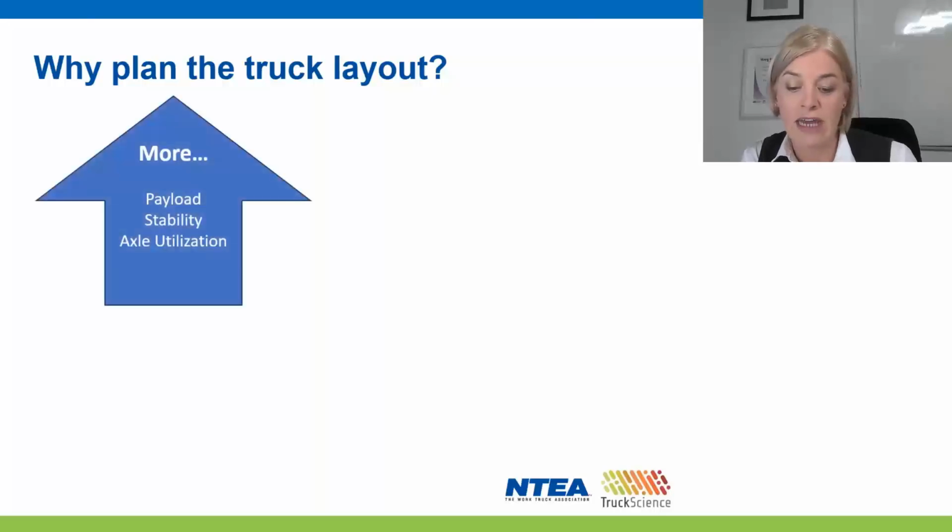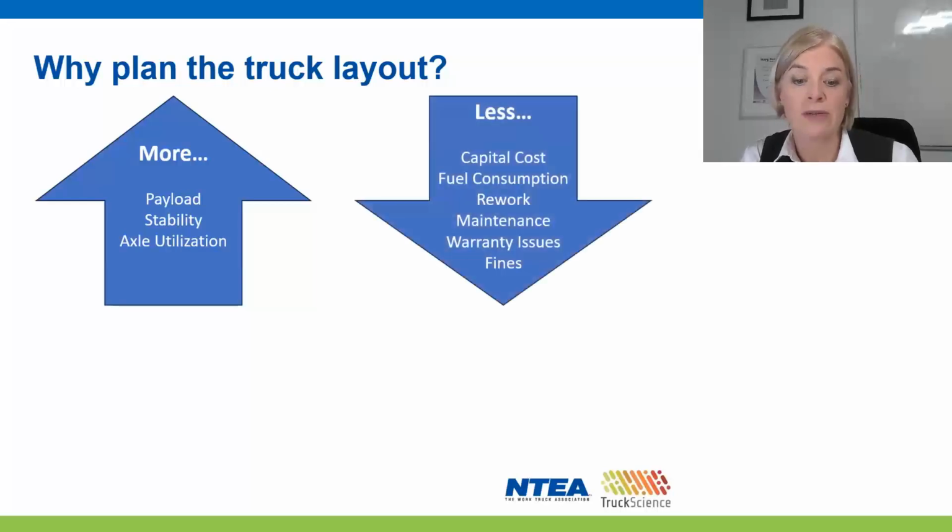Performing weight, center of gravity, and payload analysis before embarking on a truck build helps you to achieve higher maximum payload, better vehicle stability, and optimal utilization of axle capacities. It should also contribute to decreasing capital cost and fuel consumption through right-sizing the chassis, minimizing unforeseen issues that could result in costly rework, maintenance, and warranty issues, and not to mention avoiding fines.